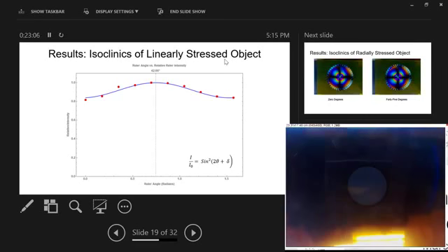And it had a maximum value at 42.66 degrees, which means that when our ruler was oriented at 42 degrees inside our polariscope, we had a maximum intensity coming through. Which, if you remember that the predominant direction of stress corresponds to the minimum intensity, tells us that if we just add 90 degrees to this, or subtract 90 degrees, we'll get to, or I should say 45 degrees. Yeah, 45 degrees. We'll get back to what would be the effective angle of our predominant direction of stress.